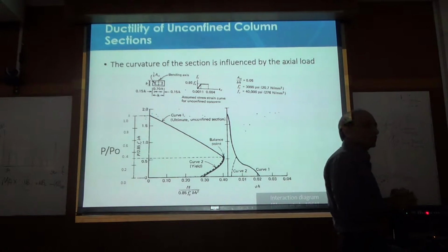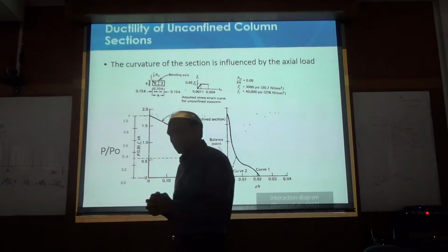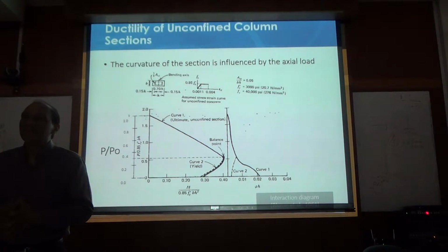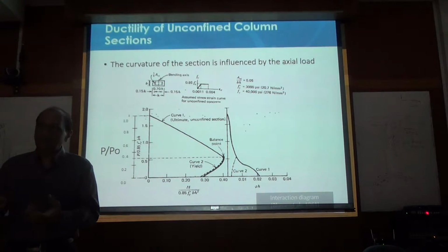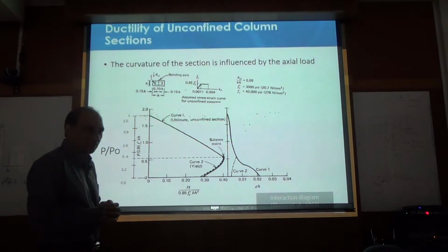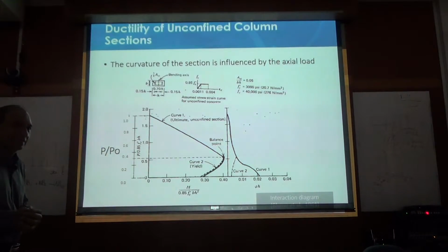So what is the solution to such problems, by the way, as an exercise? What do you think? If you are caught in this situation, what do you do? We can increase ductility by other methods. Like, for example, providing transverse reinforcement is one idea. That's good. Confinement can be increased. But that again has a limit. Whatever you do, axial load will still be a problem. But true, we increase the confinement as much as possible, go to the maximum. And then, good idea. What else can we do?